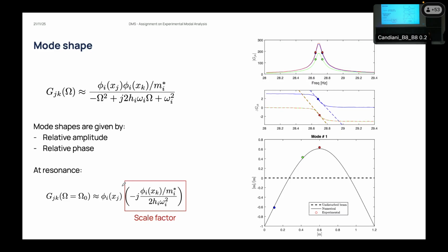If by applying a single force you are looking for the output, so for the response of the system in many locations, you can reconstruct the mode. The idea is that if you are going to excite the system like here, and then you have a set of accelerometers in several locations, you can get instant information to reconstruct the mode by looking at the different positions you are monitoring the output, okay?